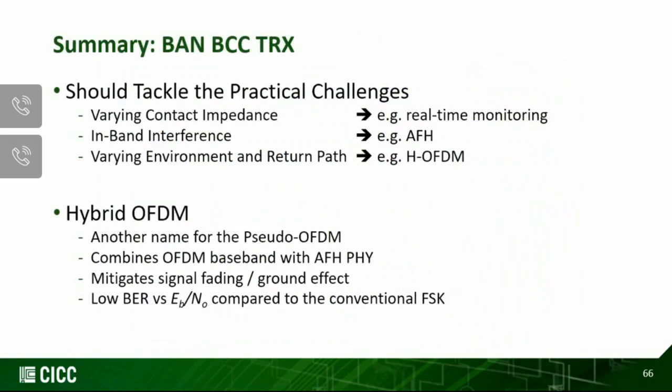Okay, let me summarize the transceiver side. The BAN BCC transceiver. The very important message I would like to give here is that we should try to tackle the practical challenges in a body coupled communication BAN. Practical challenges will include the varying contact impedance, in-band interference, and most importantly, for the capacitive coupling, more in particular, is the varying environment return path problem. So these can be mitigated with the real-time monitoring of the impedance and adaptation, and adaptive frequency hopping for the